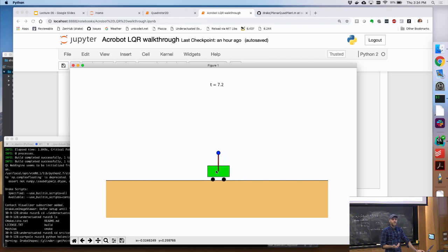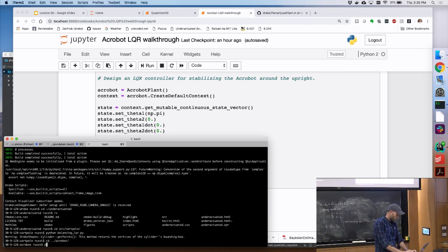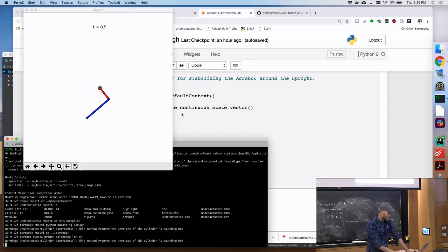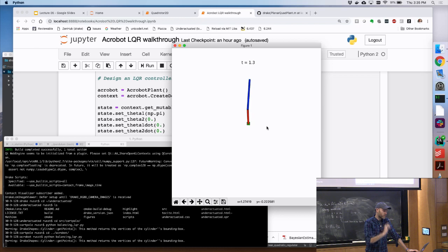Now the cart-pole is actually relatively easy to control in the sense that the linear feedback does well for a large portion of the state space. So if I plot that vector field, it actually works for a big part of the state space. The acrobot is a little bit more squirmy. Same code, except you call acrobot instead of cart-pole at the beginning. And I'm going to start small initial conditions away from the top, but this time your mileage may vary.